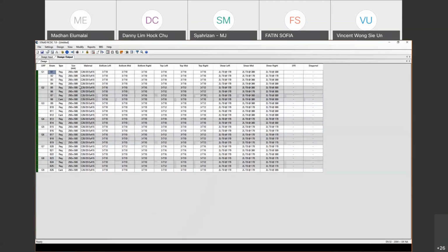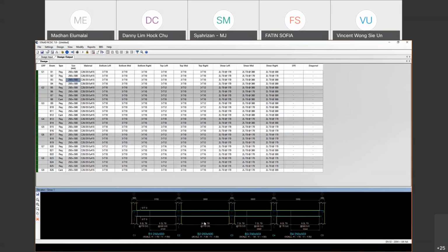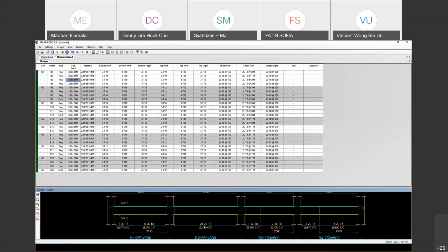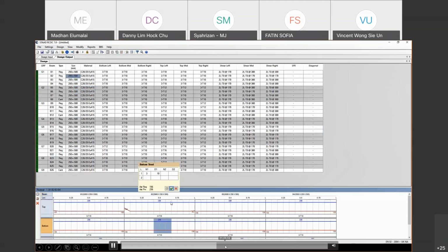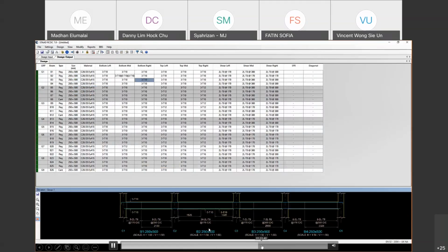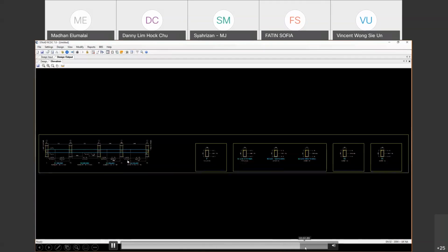If there's a beam or column you just need to design, choose the component first. In this case, we are designing the beams only. Here you can see the bottom detailing. You can change the reinforcement, and the detailing gets updated and the capacity gets updated. So the program-designed reinforcement can be modified by the user to check with a different reinforcement.